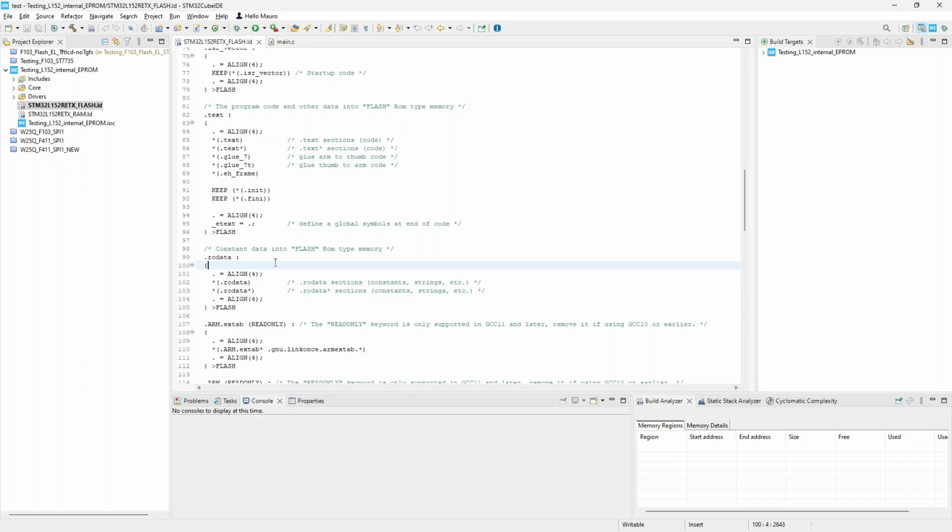Now, in a project, other than the running data lost when the system is powered off, and the constant data defined in developing the project and stored on flash, we can have other information that could, more or less frequently, need to change, to update. And we cannot erase it powering off the system. This information, that can be for instance related to the project configuration, user options, or other data to protect against power failures, can be stored in an EEPROM.